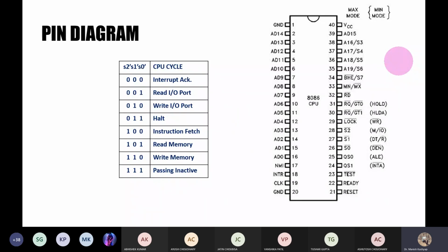So the addresses here are even addresses and odd addresses. Sometimes you will start with the even addresses, and sometimes from the odd addresses, to access the 2 memory locations or 1 memory location. So this bus high enable signal enables the higher order addresses. It is used to enable the higher order addresses, or the odd addresses, to be accessed. For example, if it wants to access only the higher order byte, in that case BHE bar will be enabled and 1 byte will be accessed. So we will see the meaning of this.